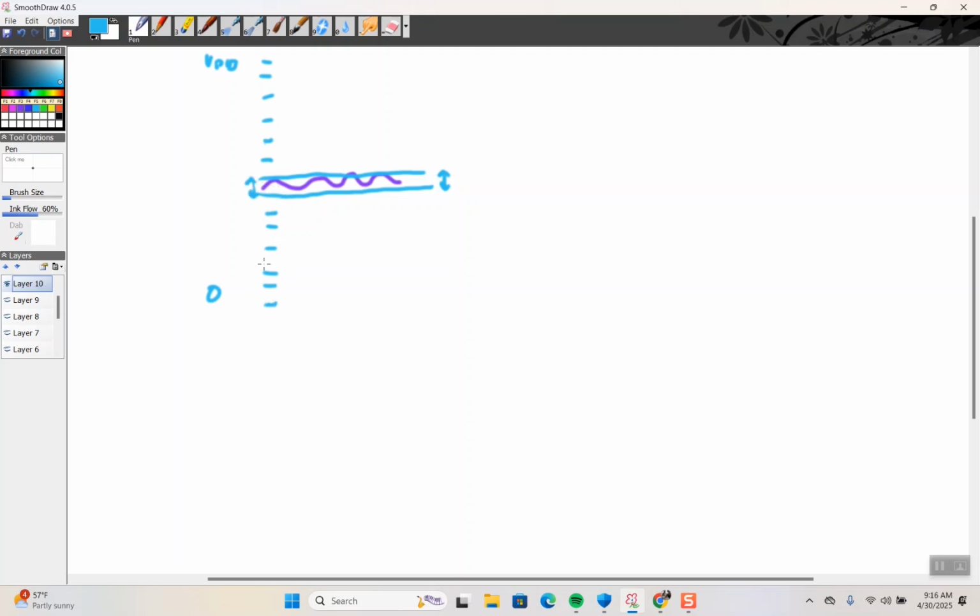That really means I have 12 levels, because this ripple is so big I can only fit in 12. If the ripple was smaller, I could fit in a lot more. So the effective number of bits is log base 2 of 12.